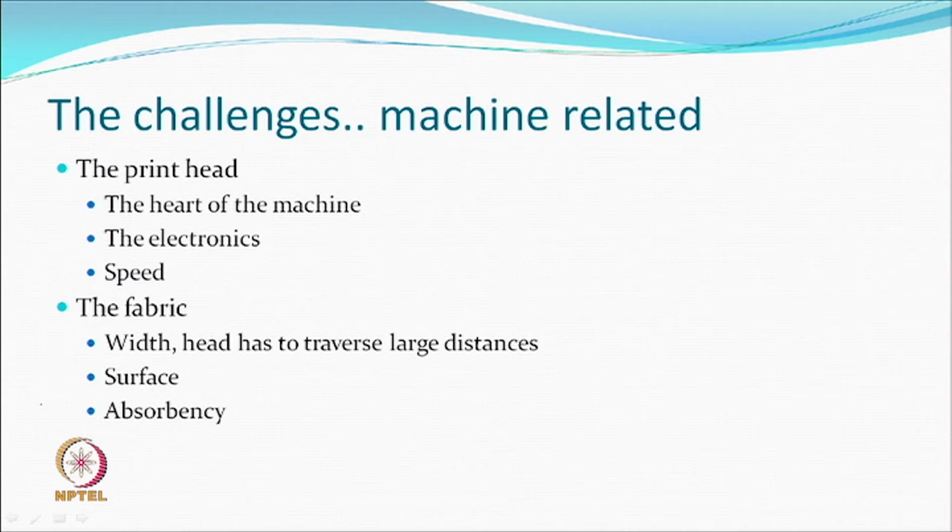The surface of a fabric is not smooth, and in case the head just touches something, the life will be bad, because while you are printing, you are just hoping that this will go and just stay there, and you will handle it at a different stage. The heads of the printer do not obviously touch it, but if there are hairs protruding out, things may not be good.